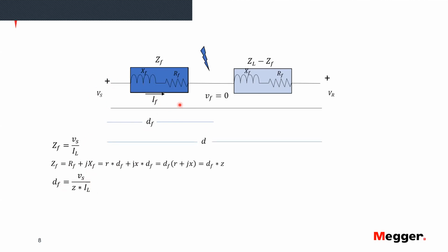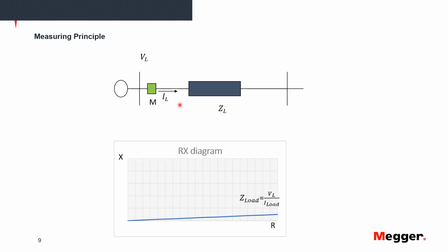So we know then that when we have voltage on a particular line and we have current circulating, if the current circulating is because of the load, typically the locus of that, let's say, apparent impedance will be closer to the resistive axis in a resistive and reactive diagram here, because most of the load we try to make circulate in the form of active power. And therefore, we are going to have a low power factor when a lot of load is being transmitted.